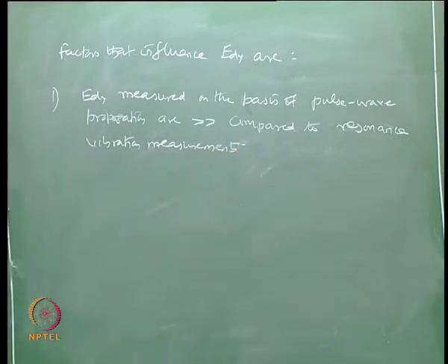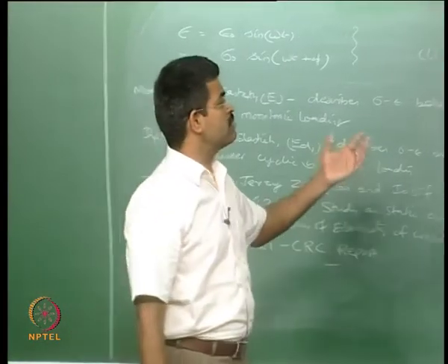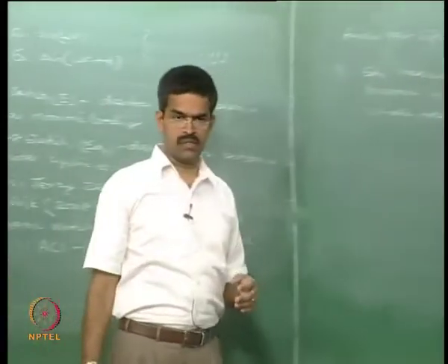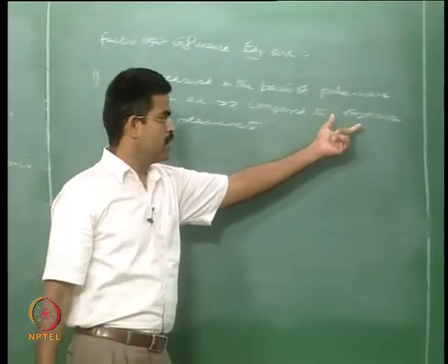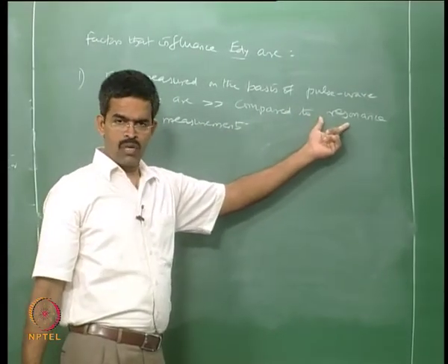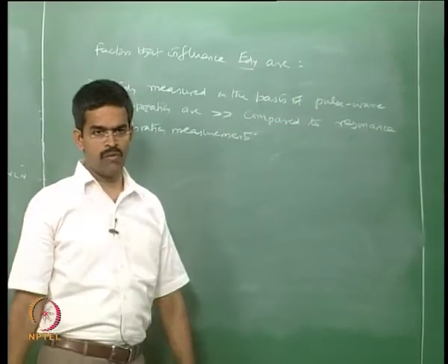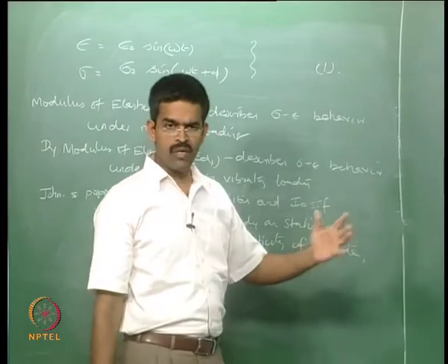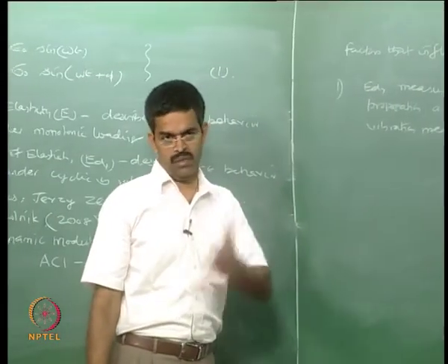So, the method by which you are estimating the E dynamic is also one important factor which influences the modulus of elasticity. There are two techniques by which one can find out. One is a simple forced or free vibration under the resonance condition, the other is what we call the pulse wave propagation technique. Both give different dynamic modulus of elasticity when conducted on the same specimen of the same material.